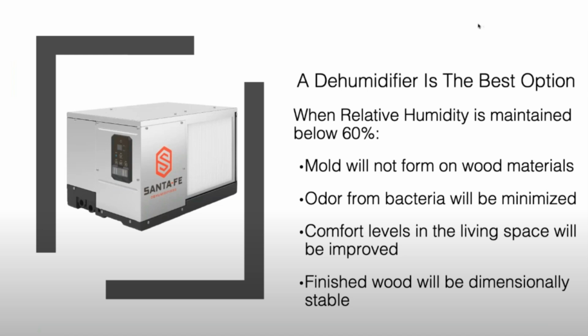Another benefit to this is if we control the RH in the crawl space, this should allow the homeowner to set their thermostat at a higher temperature because they will be more comfortable at a higher temperature with lower relative humidity. An example of this would be 95 degrees in Arizona versus 95 degrees in Florida with humidity. Finally, this helps protect the wood in the home as well.